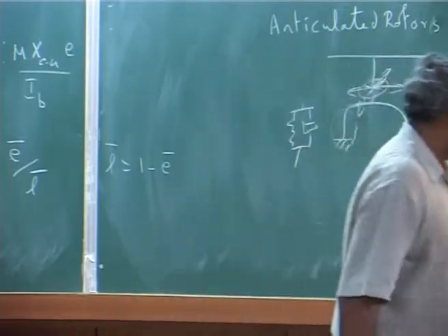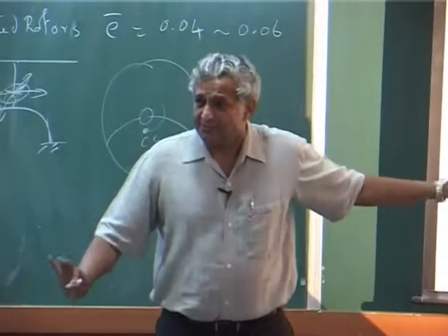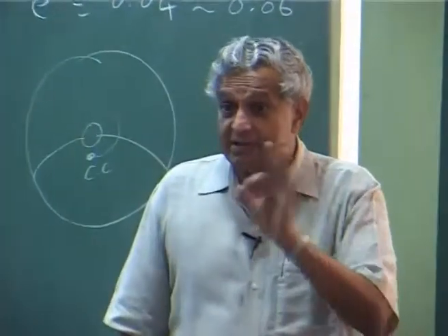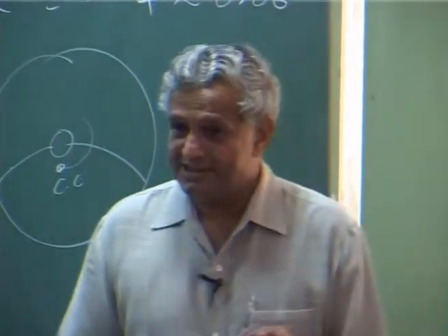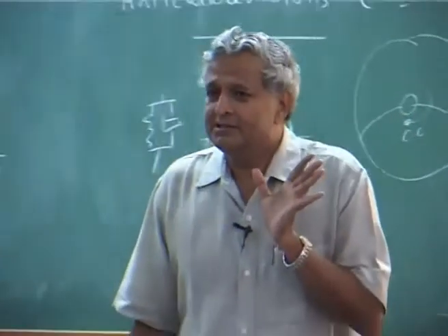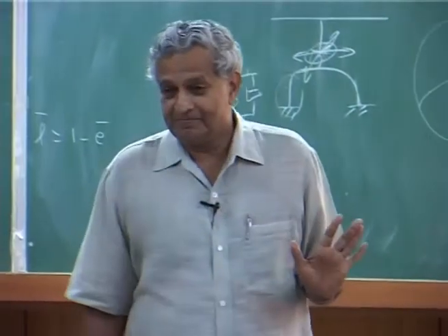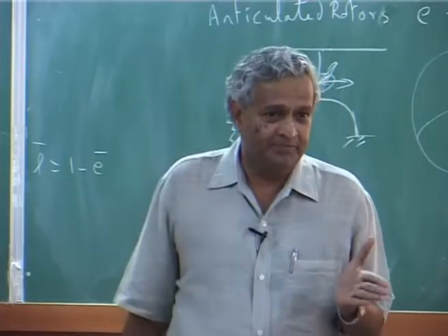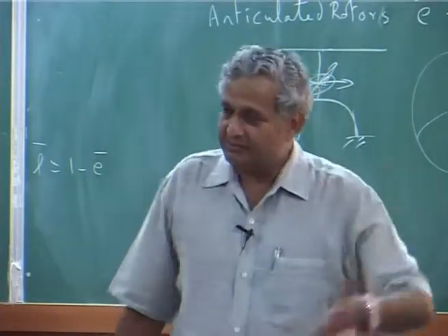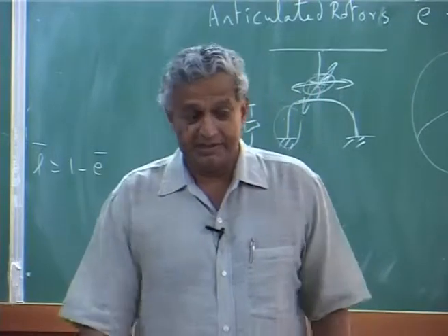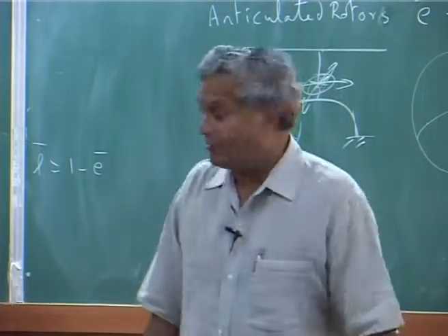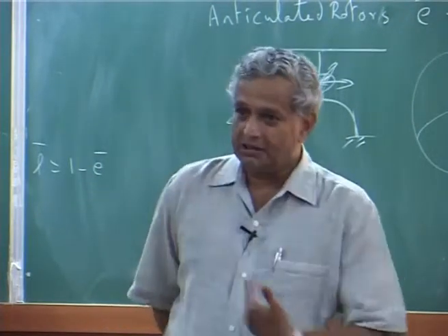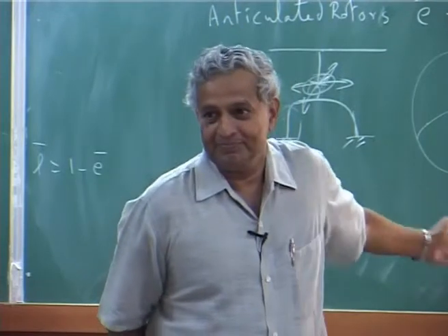Now, this much is enough for lead lag motion, isolated lag, and isolated lag is stable. Please note that if I treat only lag dynamics, it will be stable, because there is a little bit of damping that comes from the aerodynamics. Of course, if you want to put in an external damper, yes, it will be stable, but the external damper is put in only to avoid this problem, flap lag instability or ground resonance problem.